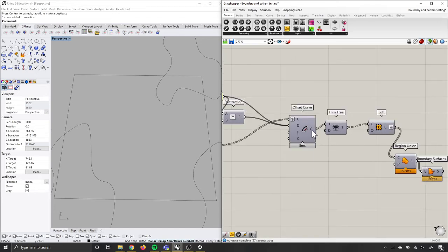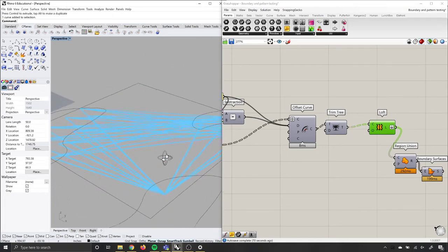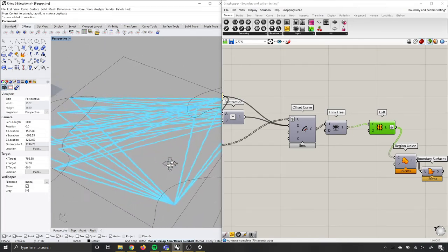Finally, on here we take this where it's all one curve for each thing, and then we're going to trim the tree. We're doing this because the offset is from these 2 values, grafting it again. This is going to take off that top branch, and it's going to just make sets of 2, so the part that's -3 and the parts that are +3 offset, and then we're going to loft them. And so this is essentially just making actual pathways.